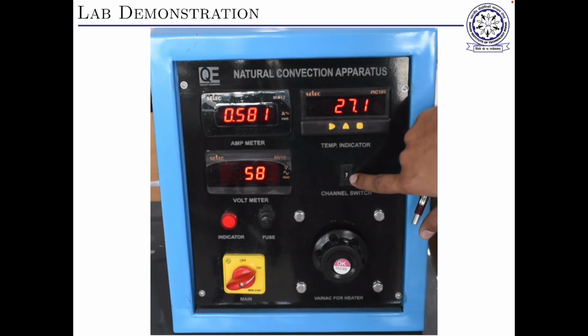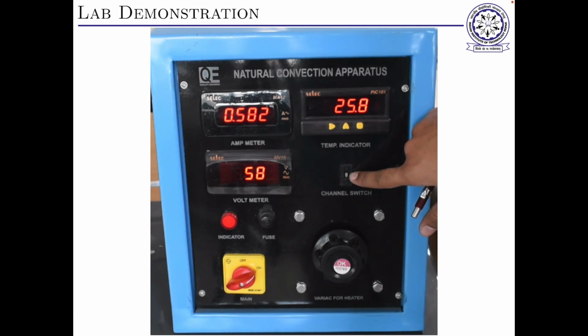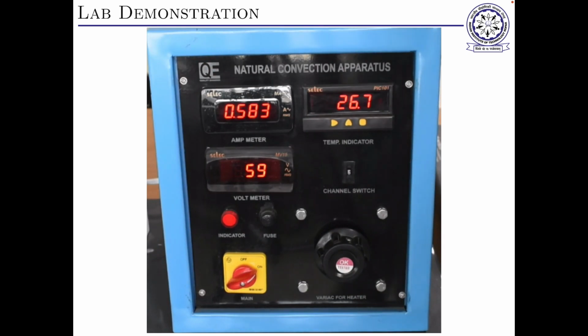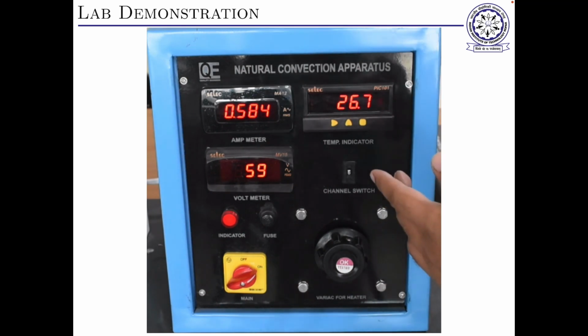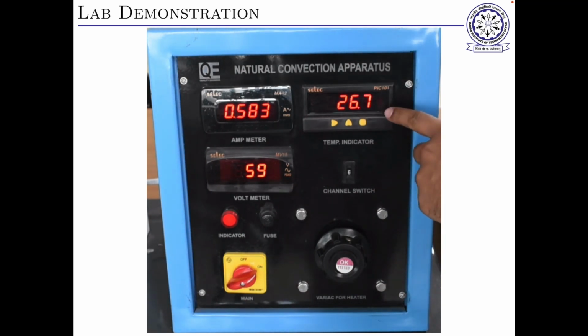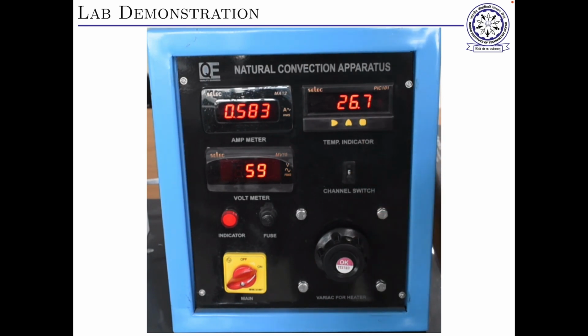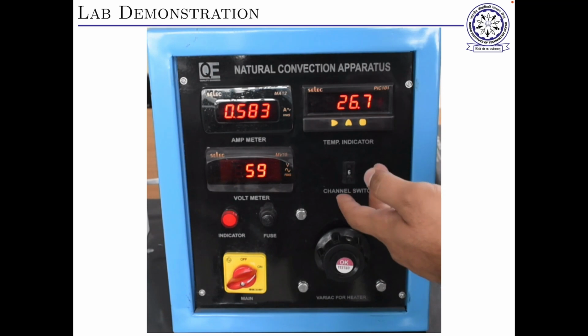Now to see the various temperatures inside, for example, this will give T8, the ambient temperature, 25.6 degrees Celsius, and these are the readings on the outer surface of this cylinder. For this experiment we only need one reading, and after some time these temperature readings will change and take a steady value, and using those values we will calculate the convective heat transfer coefficient.